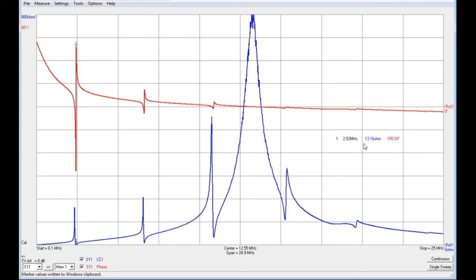And in doing that, this type of AC analysis is a small signal AC analysis, and that's something that I'll come back to, because obviously that's different from the very large signals that we actually apply from the generator. There are differences between the small signal analysis and the large signal performance, but we won't worry about that too much at the moment, since we're looking at how to use the VNA to give us an idea of what the overall input impedance would be.